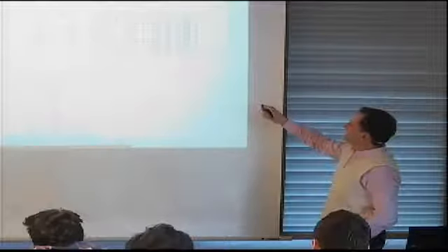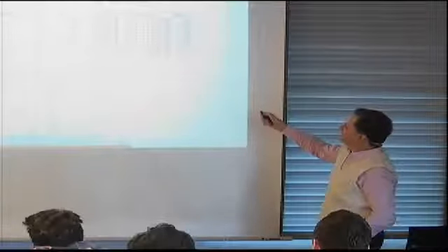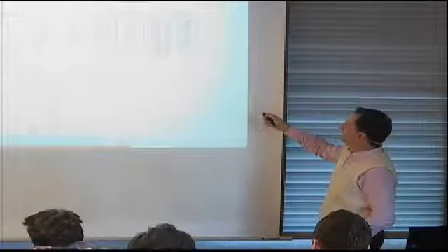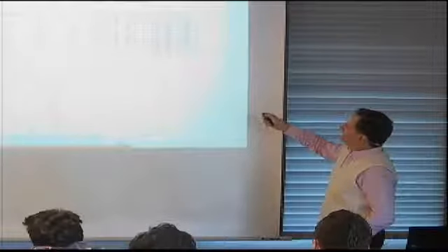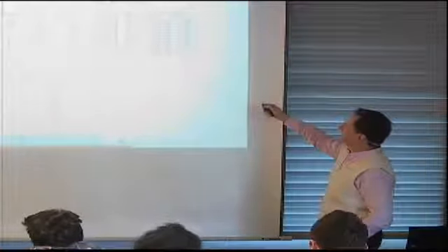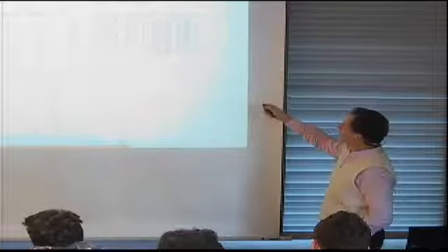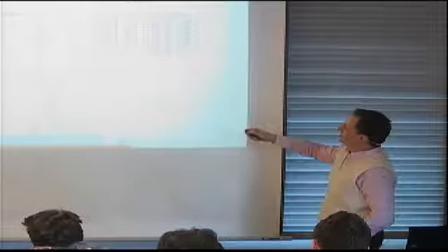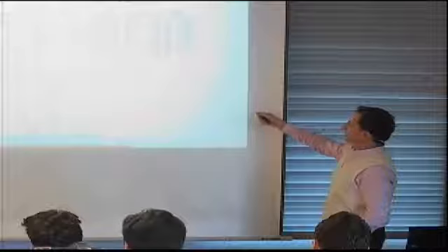And it's telling us that members 3 and 4, which are the flanges at the bottom here, take 25% of the total load each, 24.9. Member 2, which was mostly 45s, is not that effective, and carries less than 10%. Member 1 is quite good for its dimension because it's small. Look how small it is. It's carrying 15%. Our trouble area will turn out to be these 13% of the load that goes into the skin on the 2 sides of the skin.